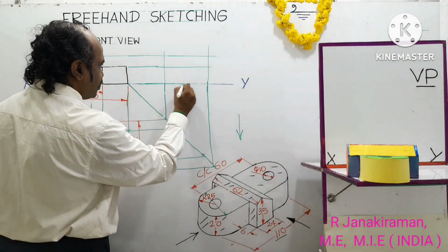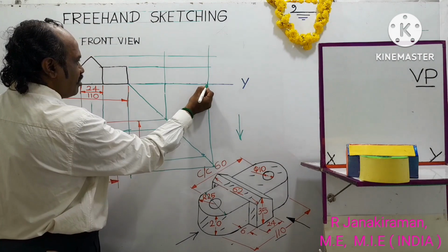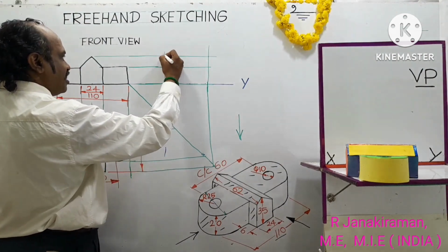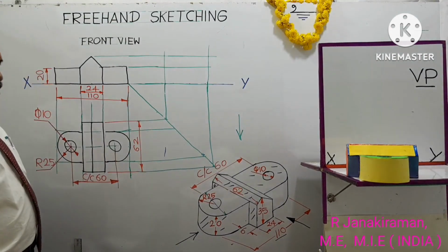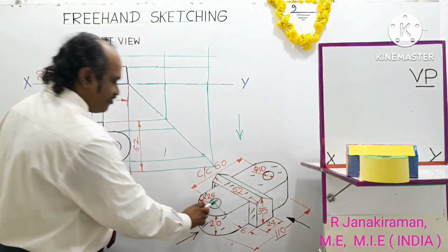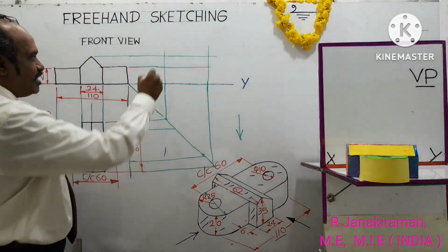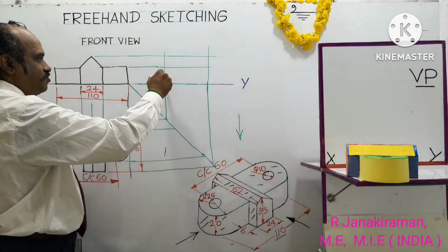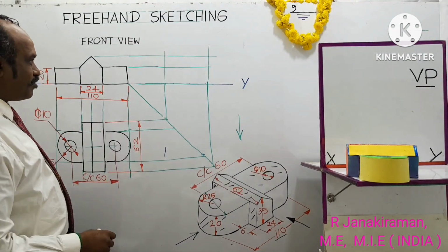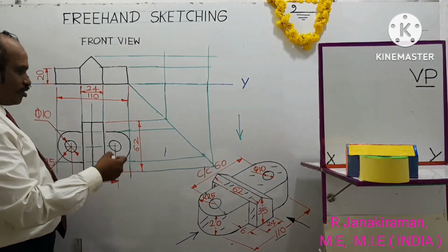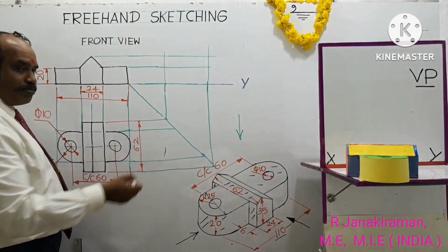The XY line is also projected. You can see these corner points. This forms a boundary for the left side view. So looking in this direction, called the left side view direction, only inside this boundary will the side view come. Okay, that's how the maximum boundary is fixed. Then you also project the center line. So let me project.